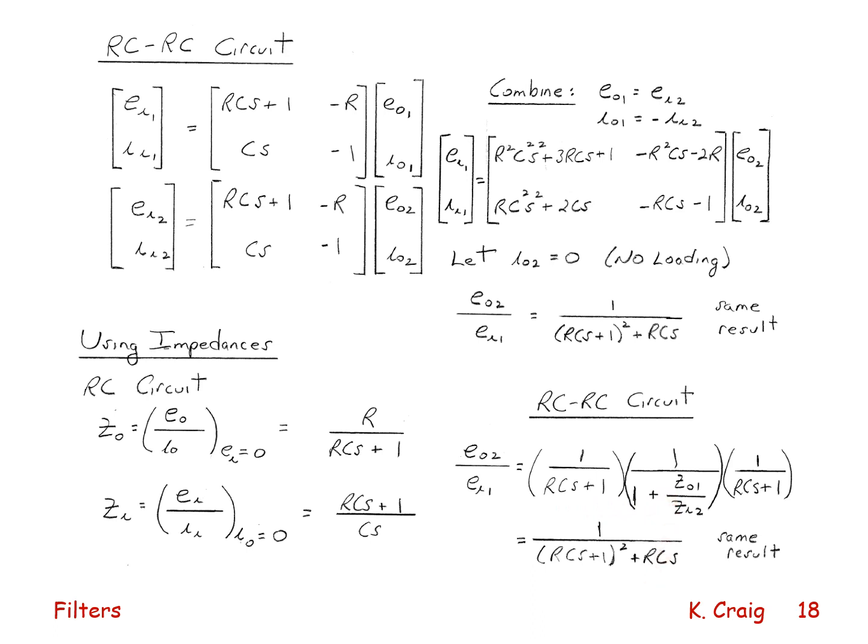So here are three different ways you can identify the overall input-output relationship for an RC circuit: either from first principles, or by using the complete matrix description of each RC circuit and combining them mathematically through matrix multiplication, or lastly, by using input and output impedances.